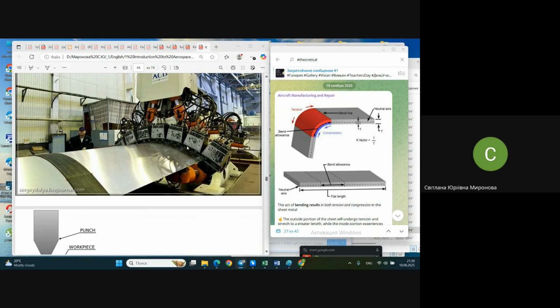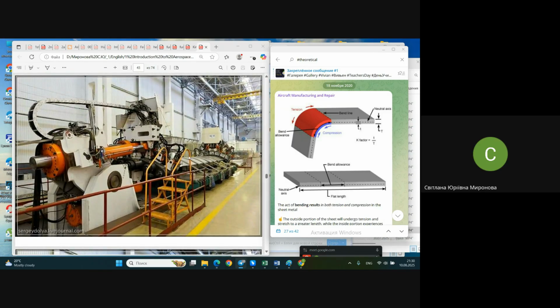Truth also that not all of this part is finally usable, and the piece of sheet that we place on such a punch in such a machine is much greater than the part that will finally be cut from it. But there is no spring back effect, and we save much money on tooling because only half of the tooling is necessary in this process. It is of course usually used for big parts, not for little ones.